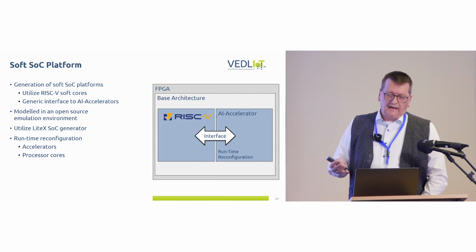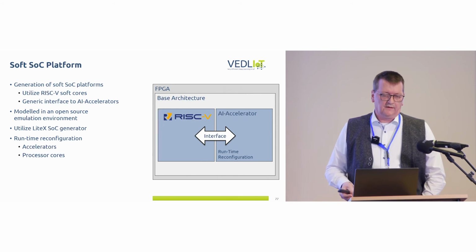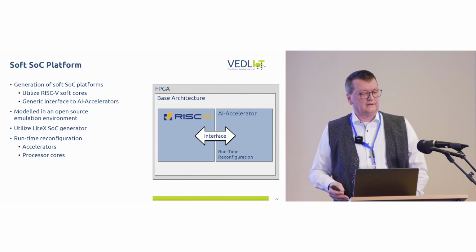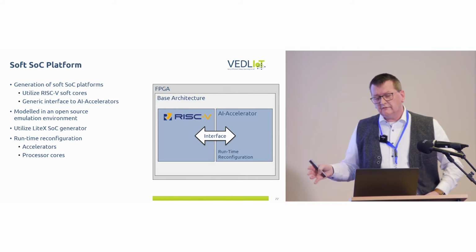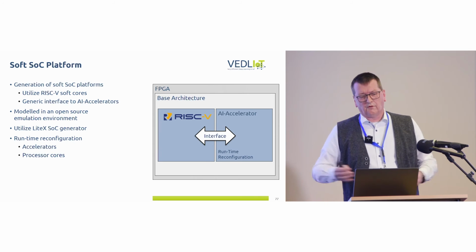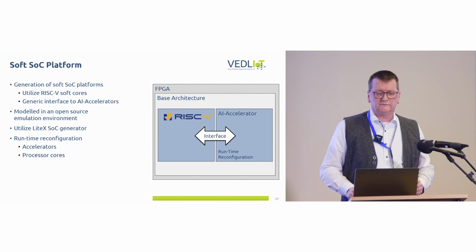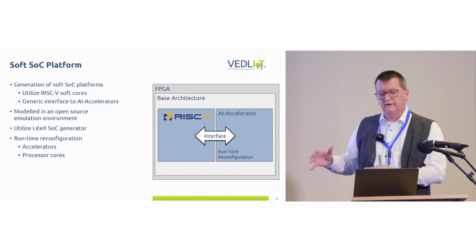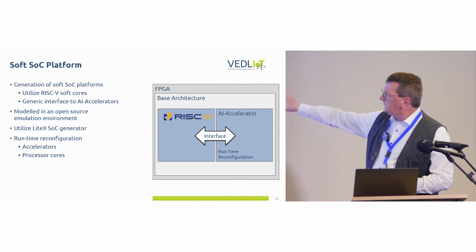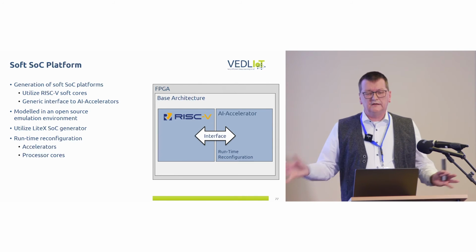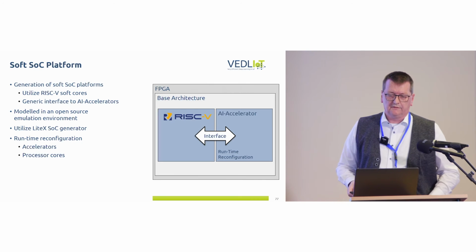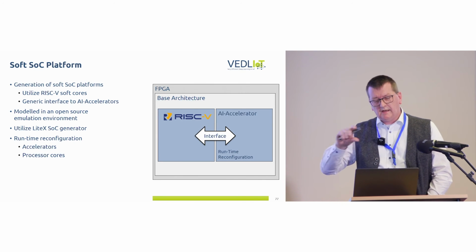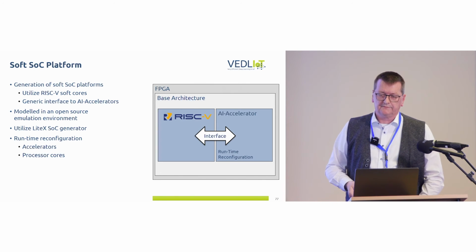So the SoCs will be generated utilizing the open source LiteX SoC generator. And the interesting thing here, not only that it's all open source, but thinking about dynamic reconfiguration, we can now not only reconfigure the accelerator at runtime, but if we want, we can even reconfigure one of the processor cores at runtime, switching between different implementations.